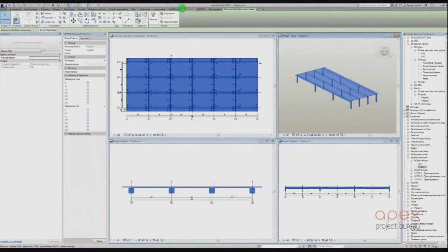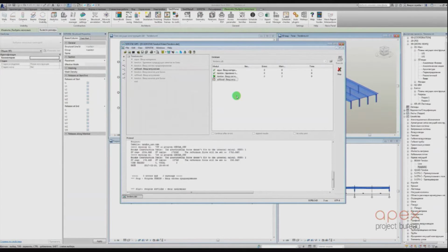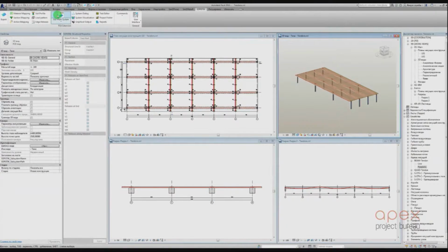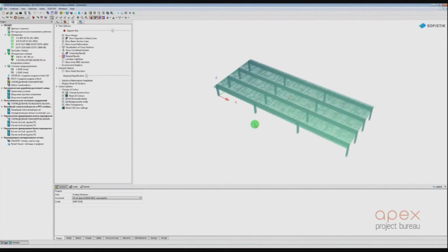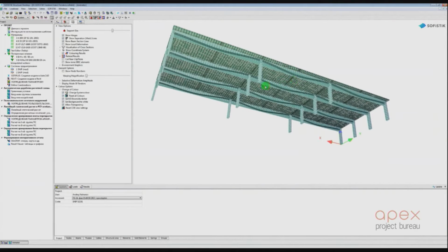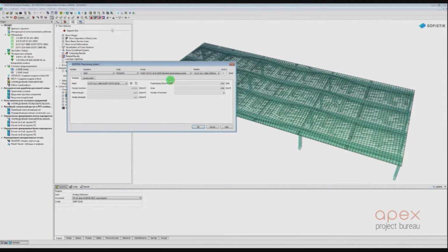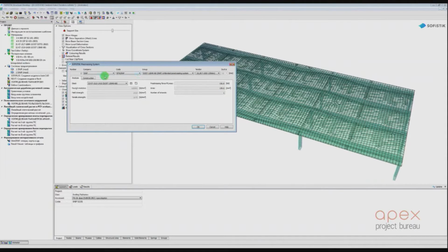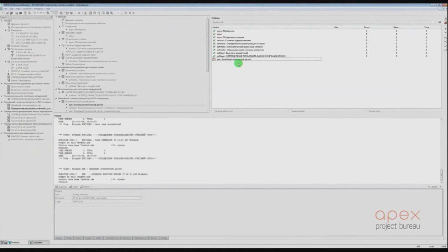After that, we use groups, although it can be done at the very beginning, then tangent export. SOFiSTiK WPS works with the codes. And here we see that we have tendons, and geometry is the same, and high strength steel is used here, and we automate routine operations. We see that everything has been transferred, bonded, unbonded systems, materials, everything is correct.